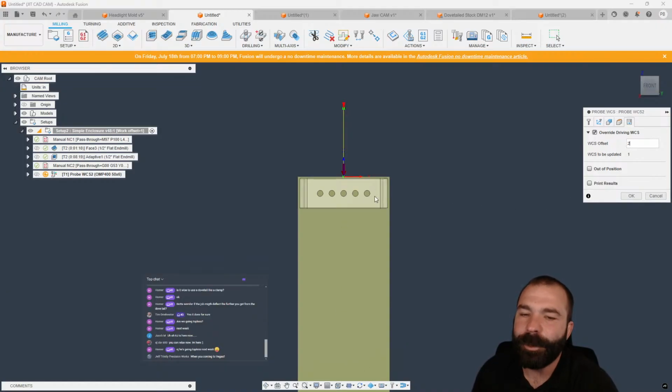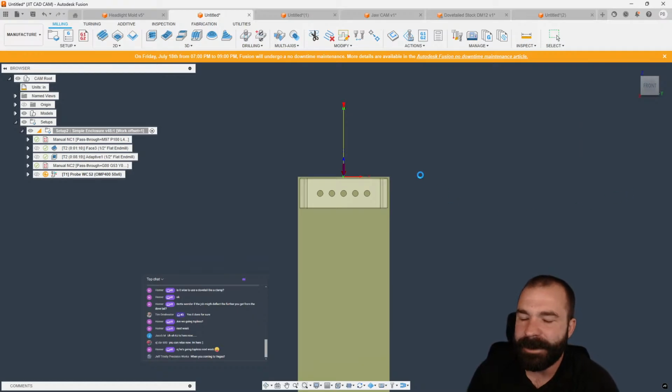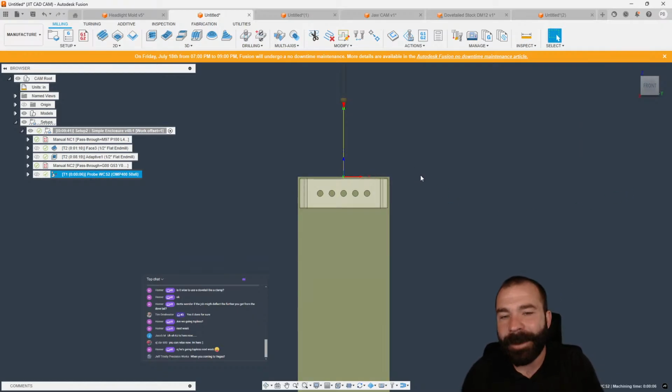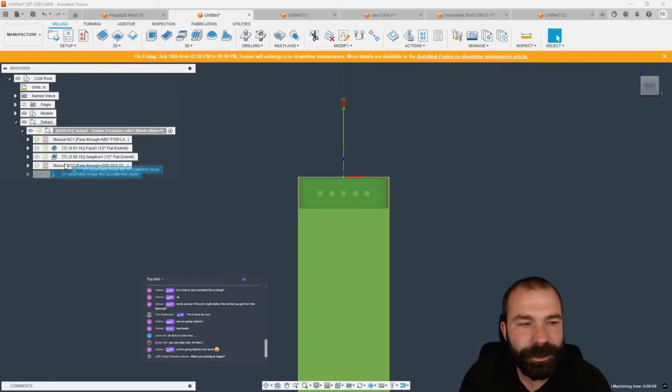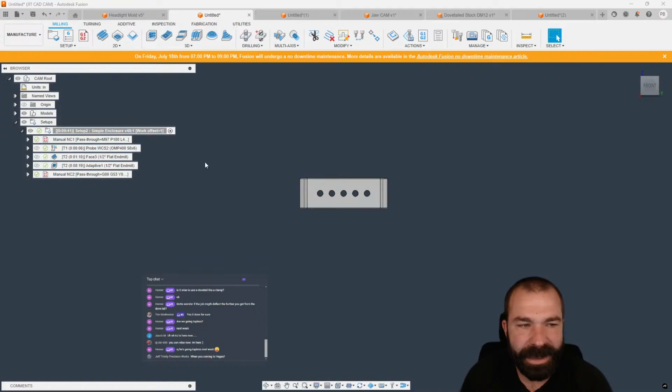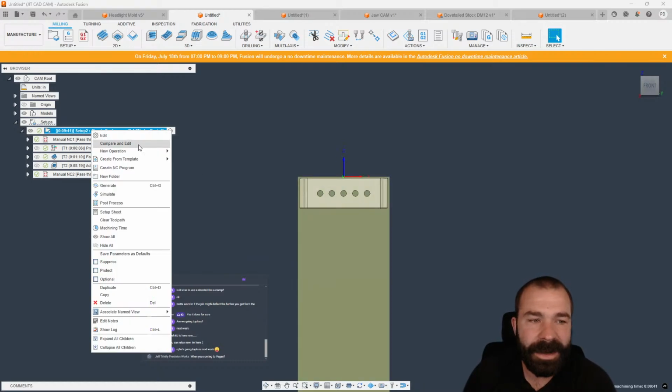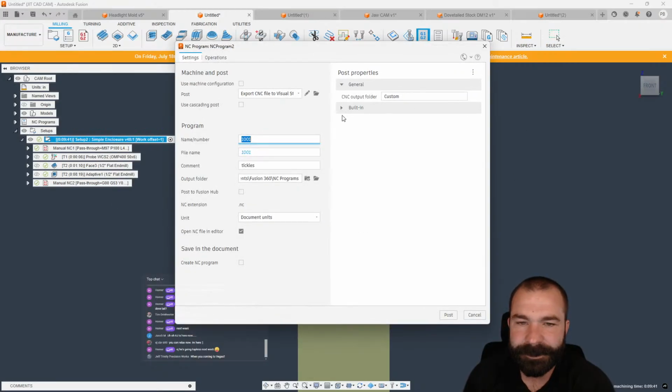And then finally, when we put the new bar in after we hit our reset, what's going to happen is that first one comes in at 55 and it hits that very top. It's going to pull 54 back up to the top, right? So again, it's not a very common workflow, but what we're doing is we are prepping everything here to be set up to be able to take one piece of material and run multiple parts out of it in a Z height fashion.